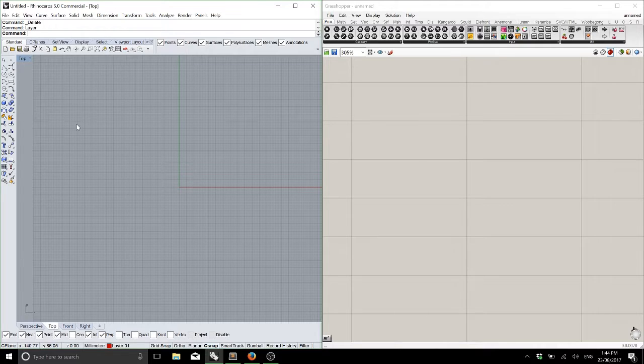But if you type minus at the beginning of any command that has a dialog, for example, save, panel, properties, anything like that, so if you type minus and then layer, then it will allow you to type in the commands instead of using a panel. I honestly don't know why your computer's freaking out so much with that. Maybe I can spend some time looking at it later, properly.